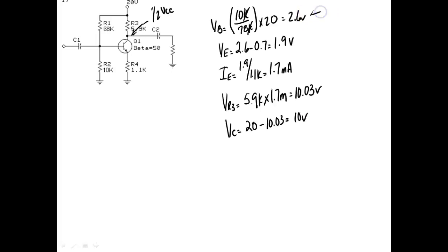We used the voltage divider formula, which you should have learned in DC. Here we used a little bit of Kirchhoff's law, right? You understand that 7/10 of a volt, we subtract from there because we know how much this guy here drops. So we know what's there and we know what this drops, so we can calculate. That's Kirchhoff's voltage law, right? This is Ohm's law, and this is Kirchhoff's voltage law for series circuits.